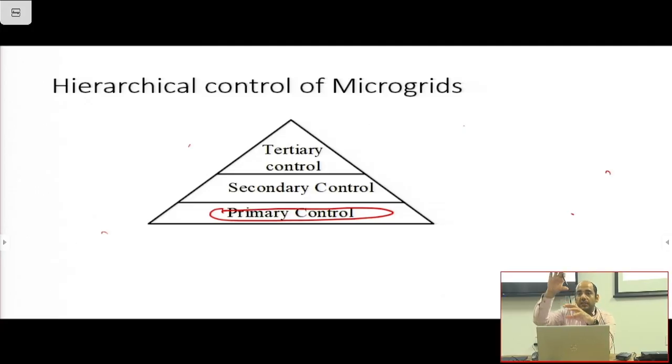So that means in the three-source system diagram that we just discussed here, if we have to throw power from the bottom to the top, we have to do something so that the angle of the bottom sources starts to lead the angle of the top source. How can we do it? We can have the bottom sources at a slightly higher frequency, or in other words, the top source at a slightly lower frequency.